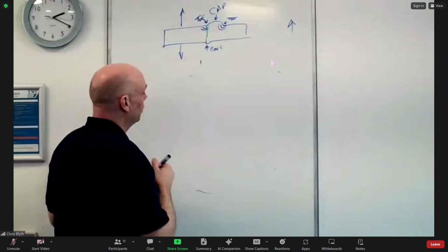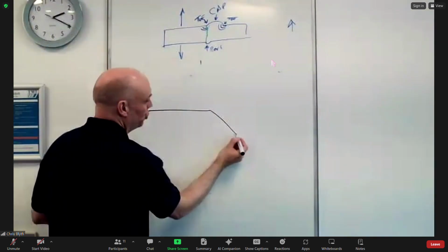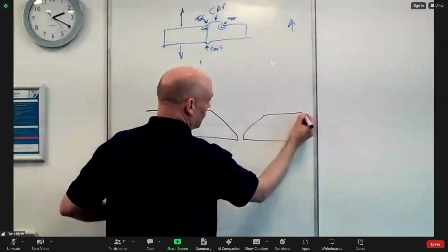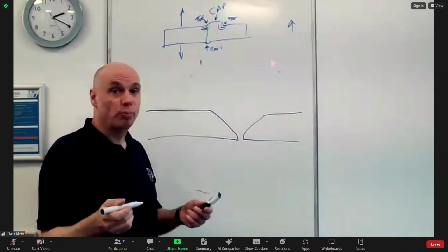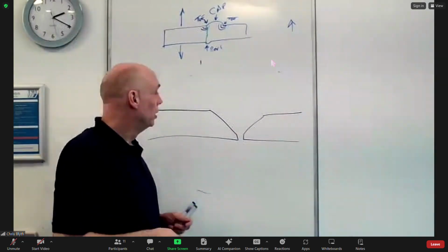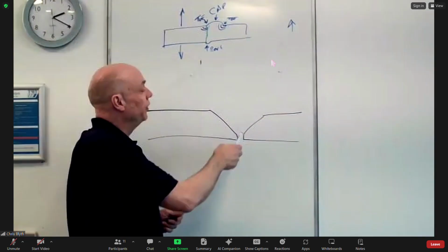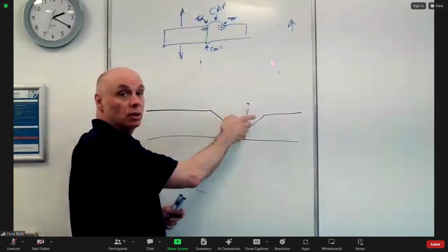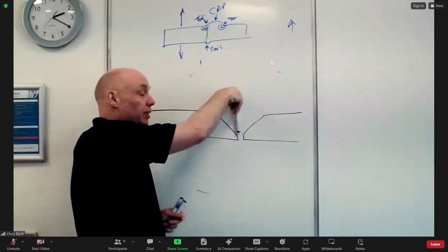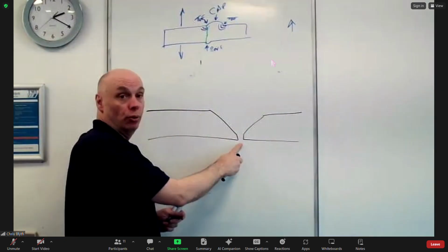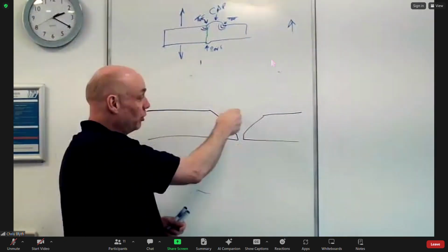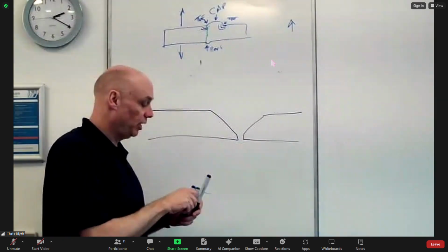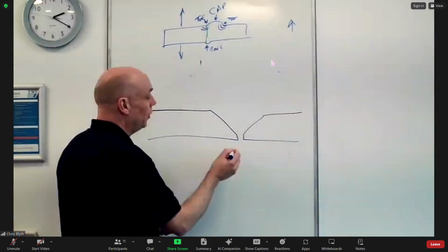So, in the first instance, you've got butt joint. Okay, always refer to the butt joint before we weld it up. Okay, so this is a single B. And the whole idea of moving this metal is so the welder can get the electrode down into the bottom of the joint, put the root in. Okay, and then we're going to fill it all back up, and we're going to put all the metal back that we've cut away.